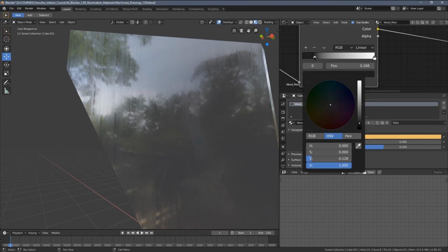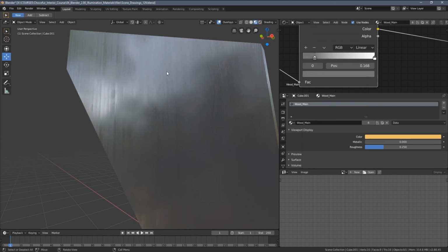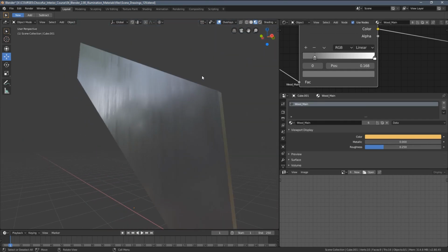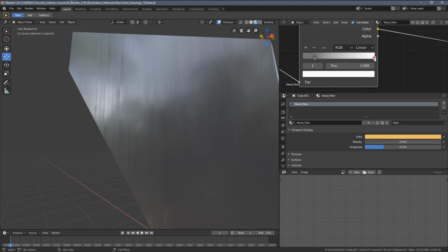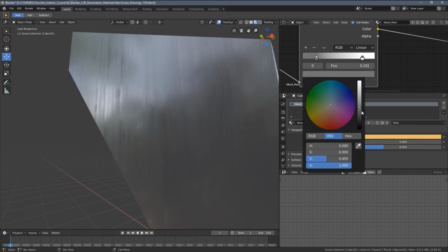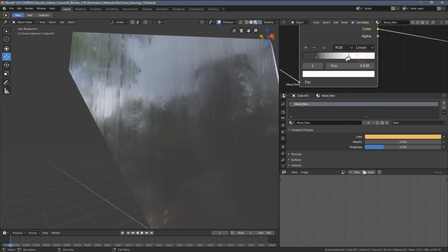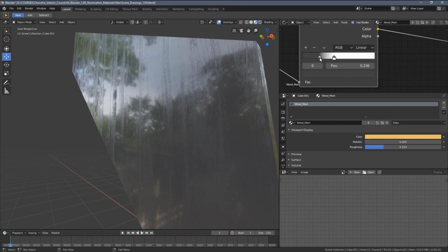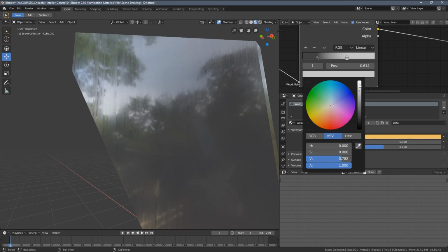With the wooden material, I want to decrease the contrast within the wooden pattern. We don't need that much contrast as with the concrete shader. I think it looks more natural if we, let's see how it goes when we do this very harsh. Yeah, I don't think it looks realistic. So let's avoid those boundary values like 1 and 0. Let's keep the white color at 0.75.